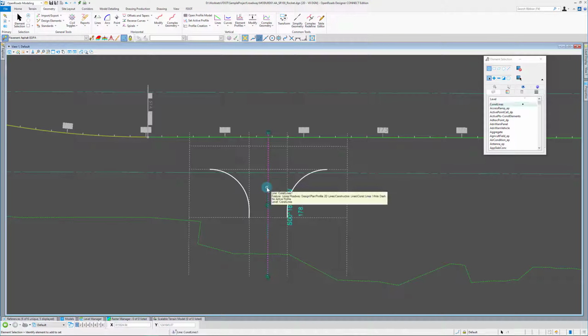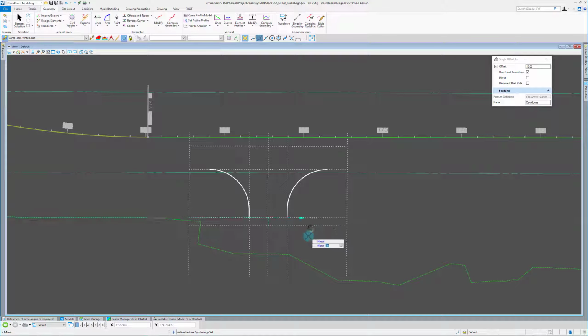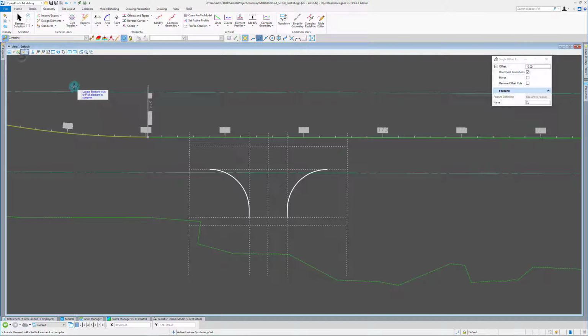So I know this is also my center of my road, and it's probably a good idea for me to set up a center line of this for later when we start doing profiling and all of that. To do that, I'm going to extend this another 10 feet just to give a little boundary. Then I'm going to select my alignment, center line. You can use baseline, but I prefer to just use the center line rule for everything. It seems to work better with all the rules.